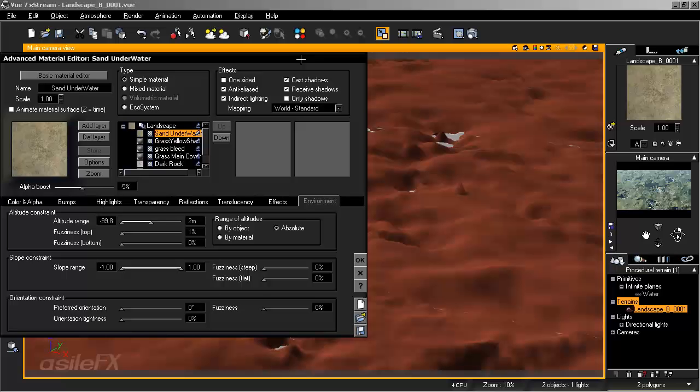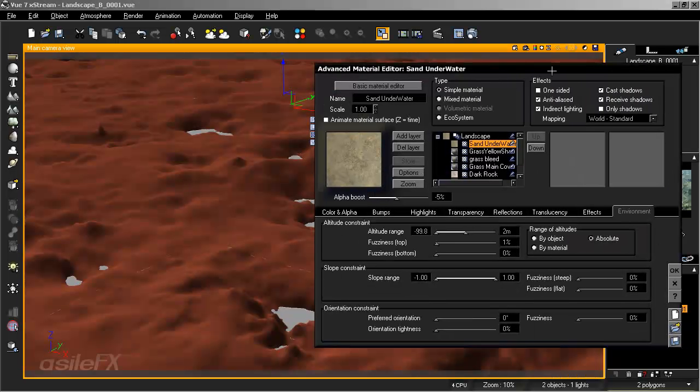So this has a nice variation of features, different points of elevation, areas with water, and that's going to be really important. In this case, we want something that has the primary features available for the entire terrain within one view. And now what I'm going to do is set a material color for each of our layers so that we can see exactly where each material is showing up, and whether or not we want to use those environment settings to populate our ecosystem.